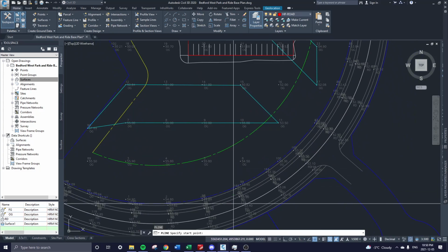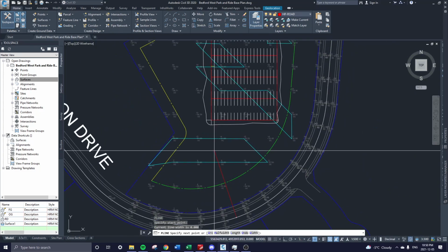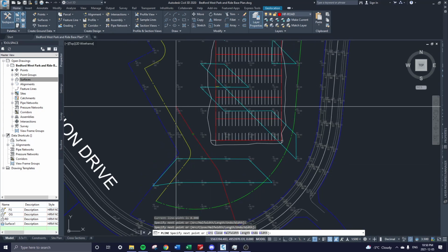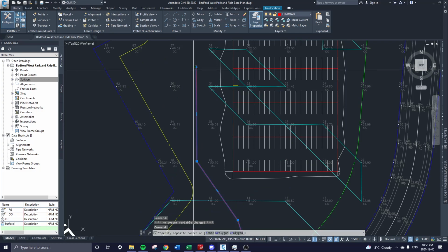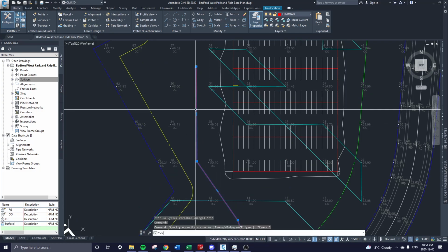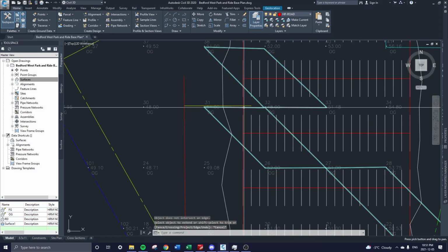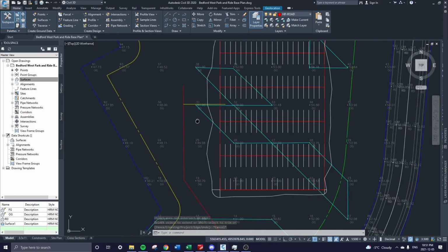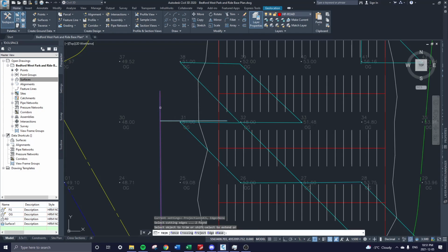So I'm going to connect it down here. You can see how it's a really silly road. You would never design it like this, but I'm going to, just so you don't copy me. Okay, so that's the center line of the road. You can use an extend command to connect it to whatever design you want. And I'm going to trim what I don't need.